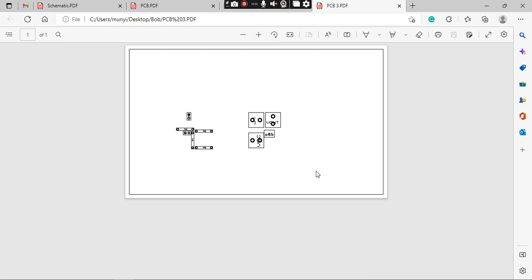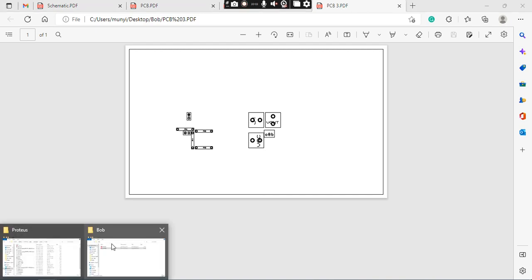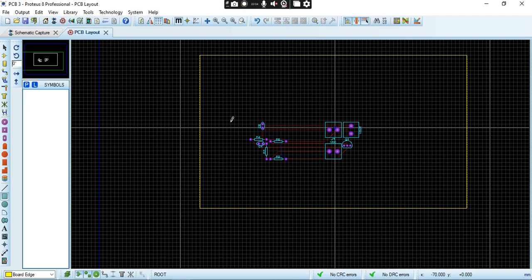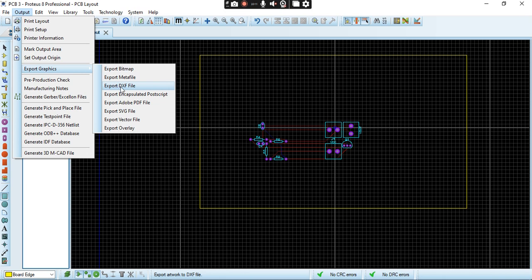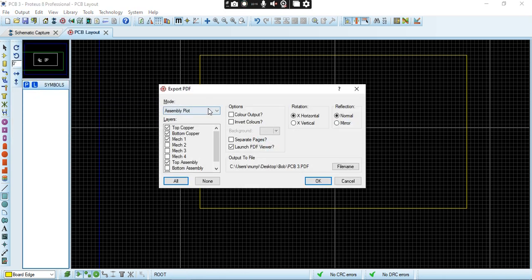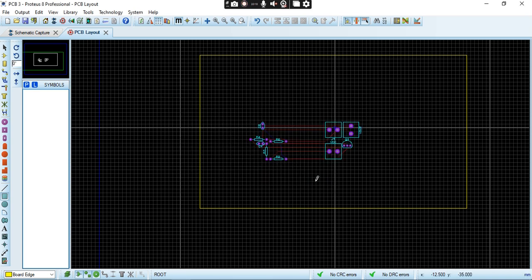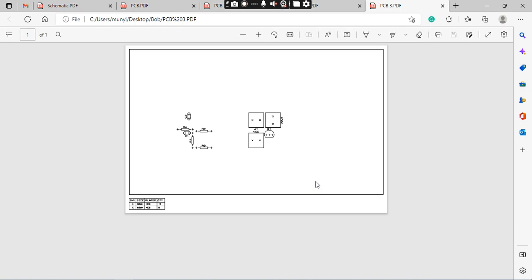All of these you're allowed to put on your answer sheet like that. So next, we can even have our drill. Remember, this PCB is used for production. So you can even have our drill plot like that, and you click on OK, and this one will show us the points where we need to drill.